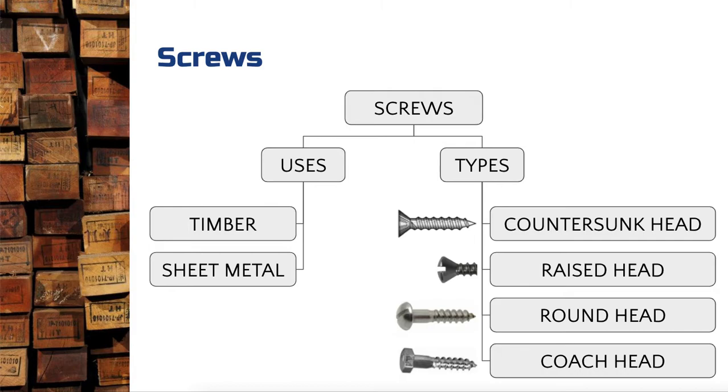You can use it to secure things to timber. Okay, that would work. So for example, trying to screw a piece of acrylic to a piece of timber, that would definitely work. But the screw itself with a thread would actually damage acrylic in most circumstances.